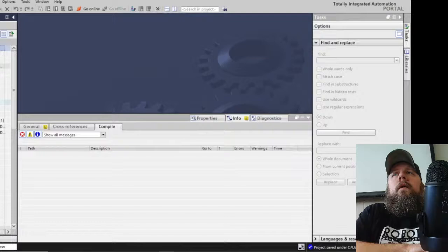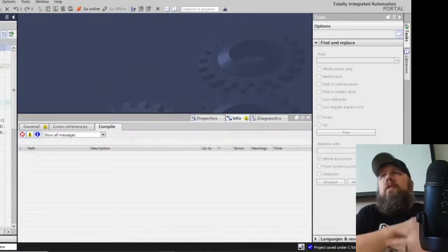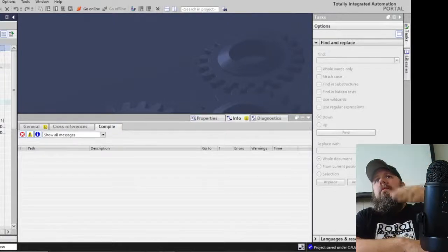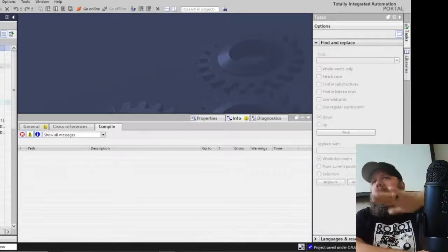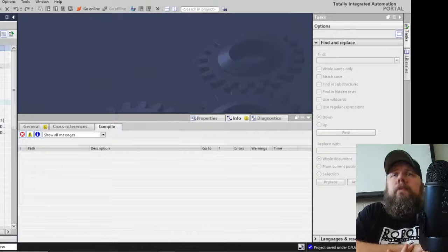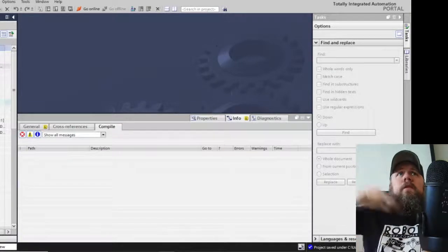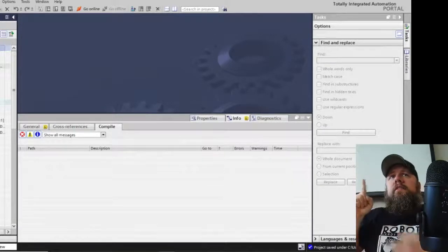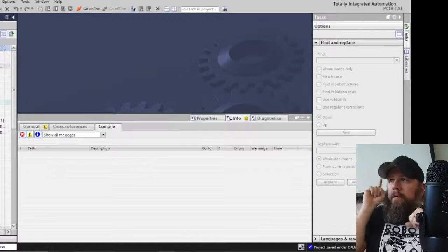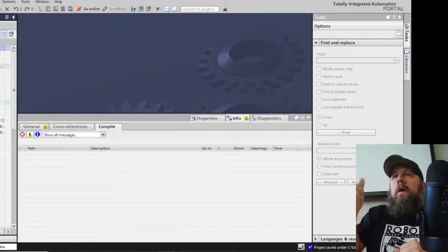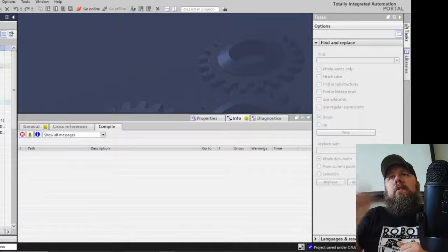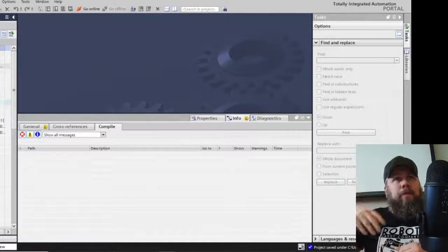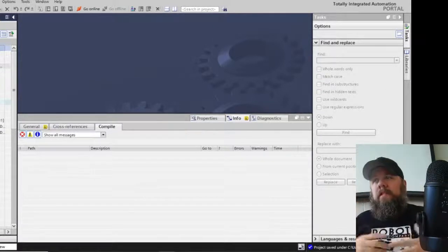But, all right, if you buy an industrial, let's say I want to measure water, okay? Like that waveguide out there is like $1,000, and it's huge. Well, did y'all see the little laser sensor I had? It's a distance sensor called a time of flight sensor, and it's pretty resolute. But they're, I think, $10 a pop. The little ultrasonic sensors that I've got, they ping out a little frequency, and then they wait and listen for it back and divide that by 2, and you can tell how far something is because of the speed of sound.